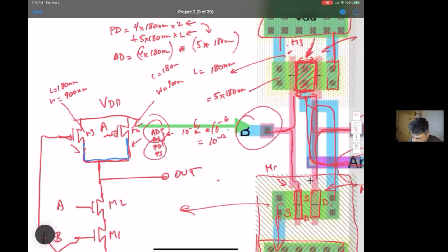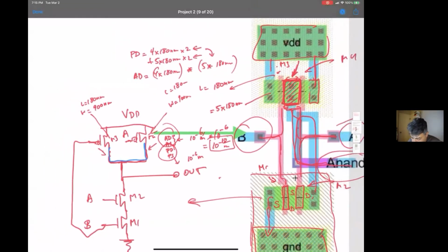Whereas perimeter drain, perimeter source are more going to be 10 to the minus 6 kind of distances, a fraction of a micron or several microns. Does that make sense? So watch out for this, because that tends to happen as you put in the wrong dimension. You don't include this stuff in your dimensional calculations. You have to remember that SPICE wants you to input stuff in meters, in this area drain, area source.